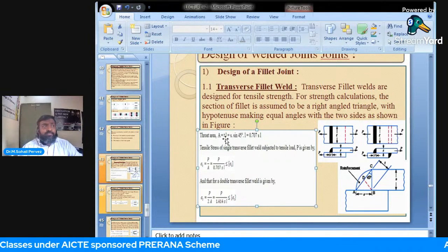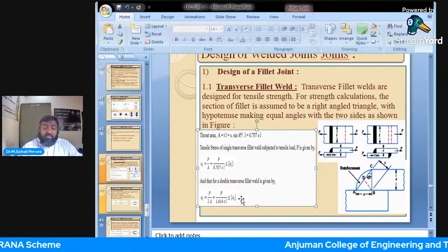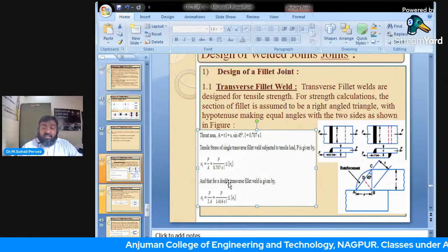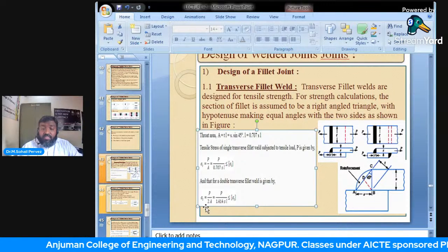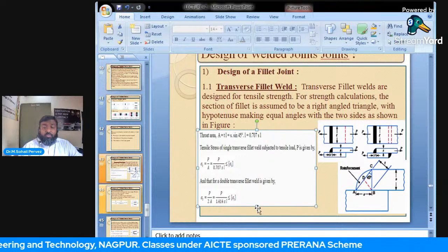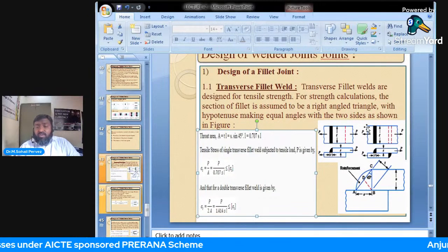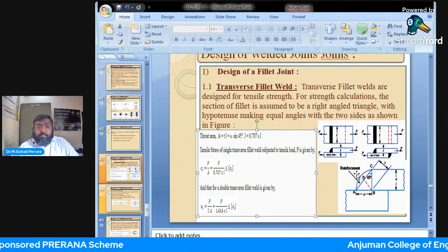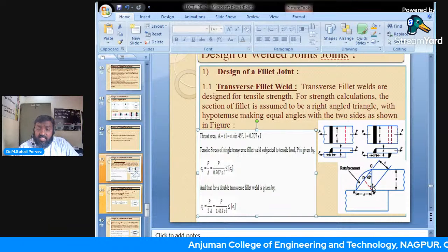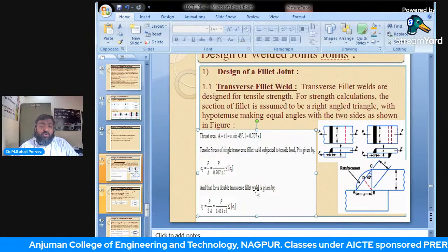L is the length of weld, the complete length of weld, and it should be less than the permissible. This is for the single fillet weld. If it is a double fillet weld, then 2 times the area, and this is the question. So I hope we have got this very basic idea, wherein what we have calculated is BD. BD is the throat length, and this throat length is converted into S into sine 45, and the equation will be...